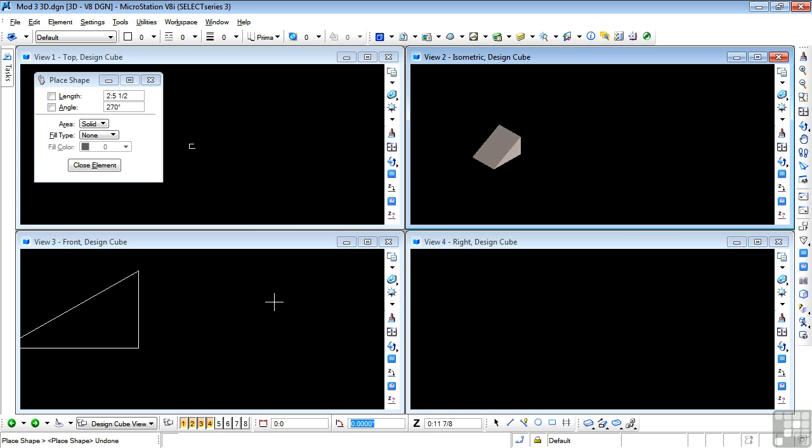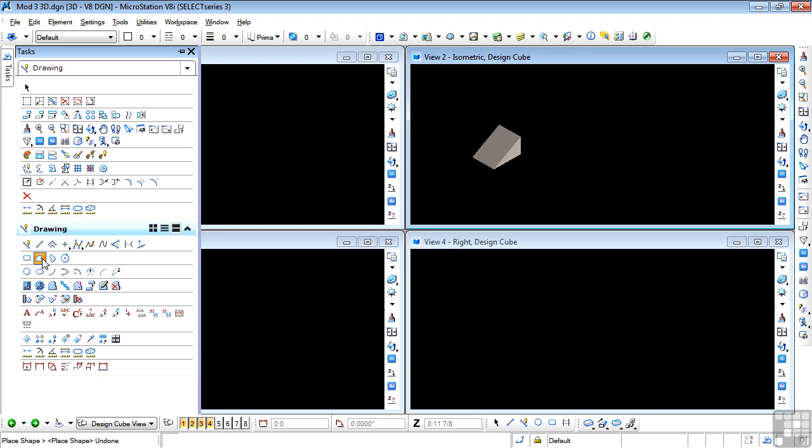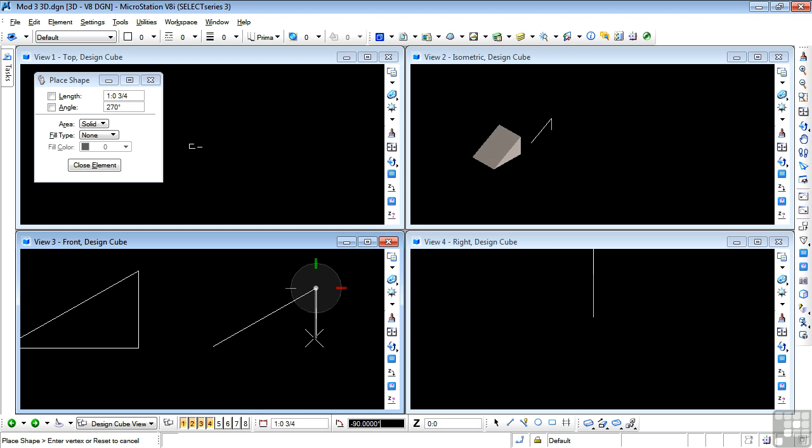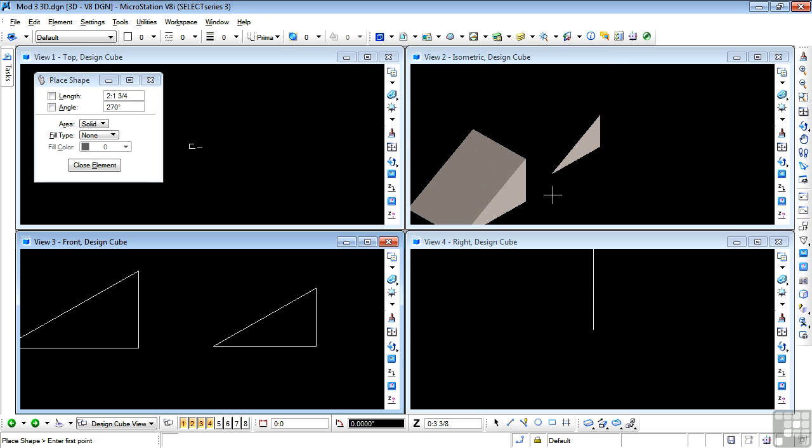Now I'm going to draw this face in the front view instead. So again, I'll use the same tool. And I'll start from the corner. Use the view orientation. Do my 30 degrees. Left click. Use F again. Straight down. I could also use the view orientation too. And Smart Lock. Back to there and there. And there's my face again drawn. Now it's not showing as a filled face here because I've not set this view to display as a filled face. So back to isometric.